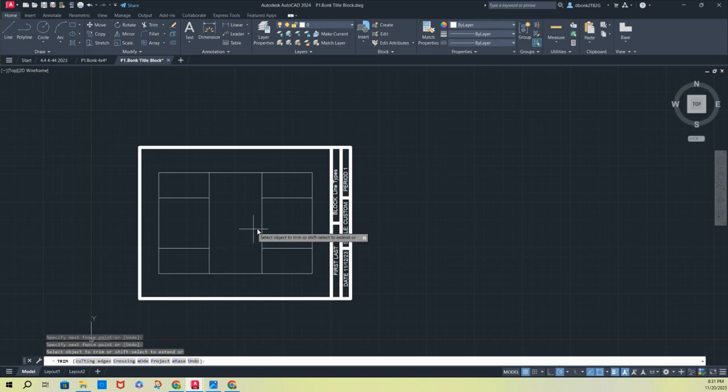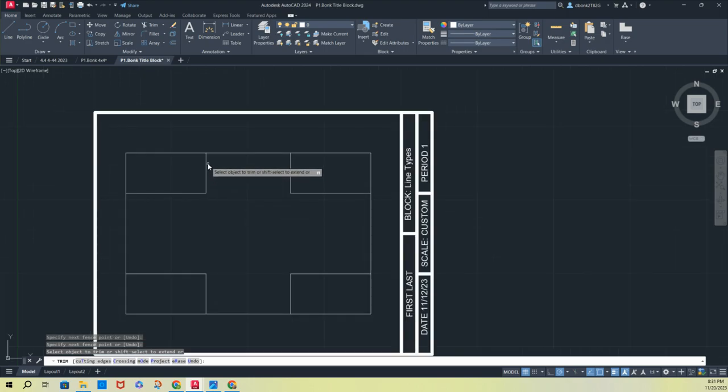Click and drag, click and drag, click and drag. You don't need those lines. Now what we're going to do is other offsets. We're making these 2 lines offset inward on all corners 3/8 of an inch. What I want to do is we want to connect these lines.